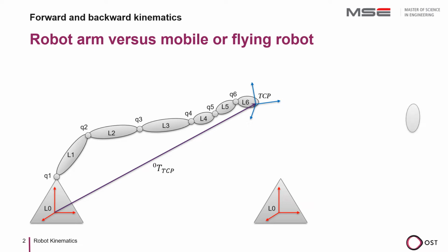The position and orientation of the tool center point TCP of a mobile robot is also described with a homogeneous transformation matrix with respect to the base. However, the tool is now not attached to a kinematic chain or robot links, which is why neither forward nor backward kinematics can be calculated. Instead, it is attached to a mobile robot that can move around freely. One cannot establish a relationship between the wheel angles and the position, but only between the wheel speed and the speed of the movement. In this case, one speaks of a non-holonomic system.